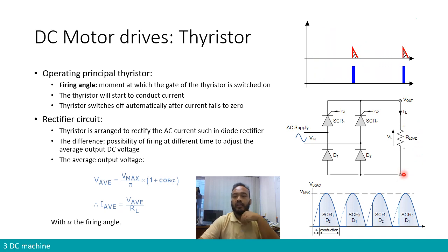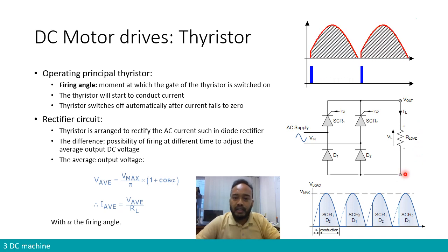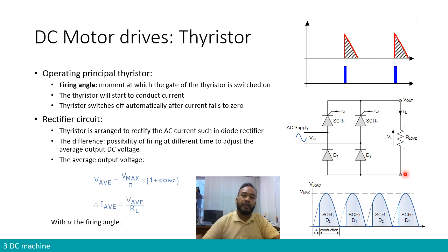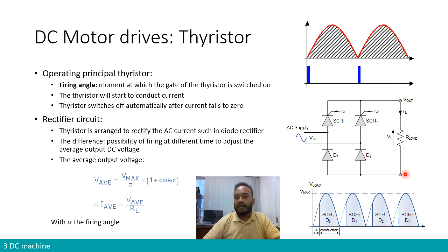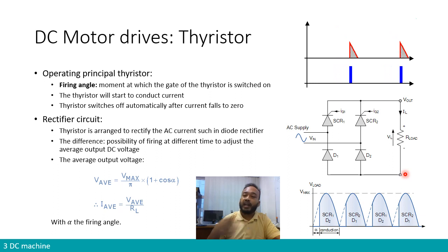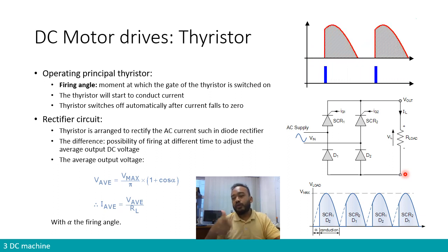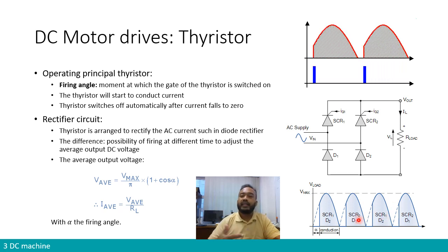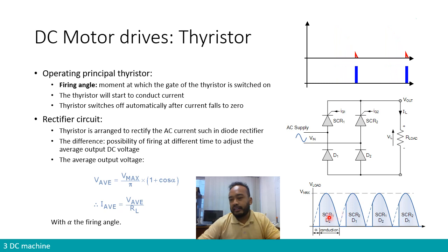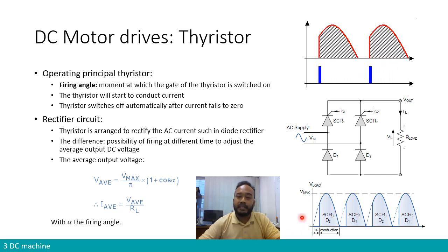Okay, so from the point of view of mechanical inertia, when we look at the machine, we cannot really see the pulsation of the speed because of the inertia of the shaft. So it continues to rotate pretty smoothly. But of course, if we take a spectrum, we may see pulsation of speed and pulsation of torque.